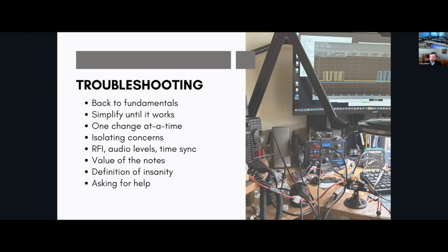So with some modes like FT8, FT4, and such, the first thing when you get in the park or try to set up, you need to make sure your time on the computer is correct. There are different ways to do that. If you're online, you can sync with the server, you can do it with GPS, you can do it using other methods through your watch and things like that.